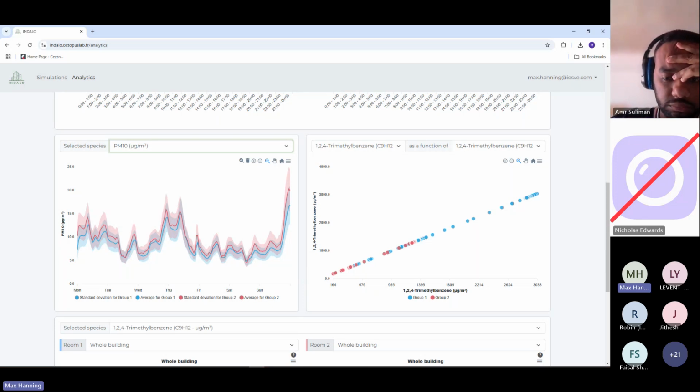So in this scenario, it appears that by increasing ventilation through our time clock strategy, we extract more VOCs and bring in more outdoor pollutants like nitrogen dioxide and ozone. So is it better to remove VOCs and bring in more external pollutants to breathe more particulate matter and less VOCs, or less particulate matter and more VOCs?